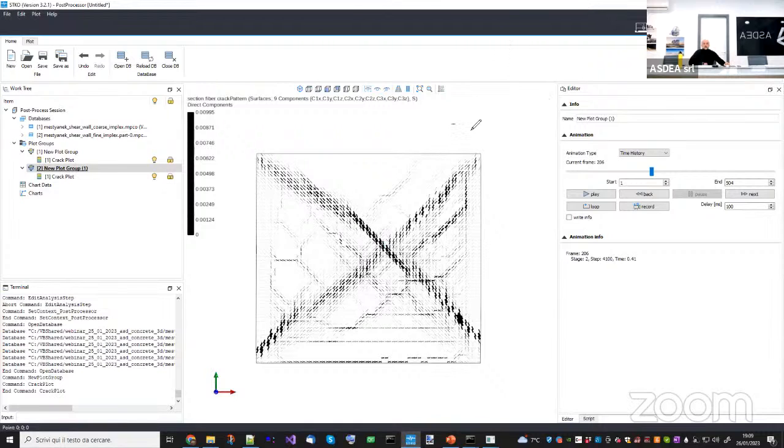So you are trying to represent a crack like this, and this thickness is 1 centimeter, okay? Now here I'm dividing 1 centimeter for a mesh. Basically, I'm representing this crack with a smeared deformation over a mesh of 7.5 centimeter. Okay, so the strain here will be this value divided by 7.5.